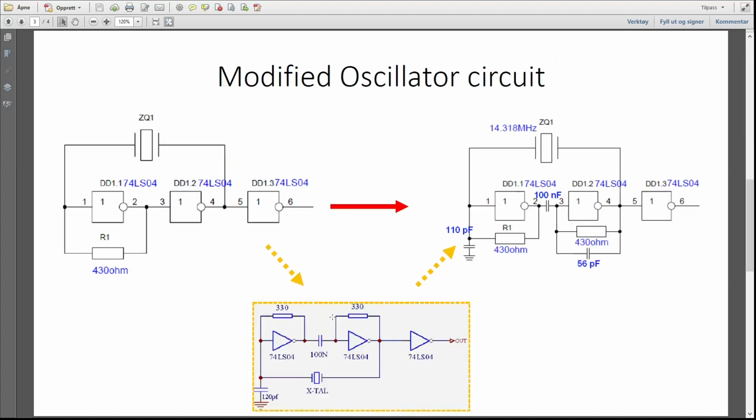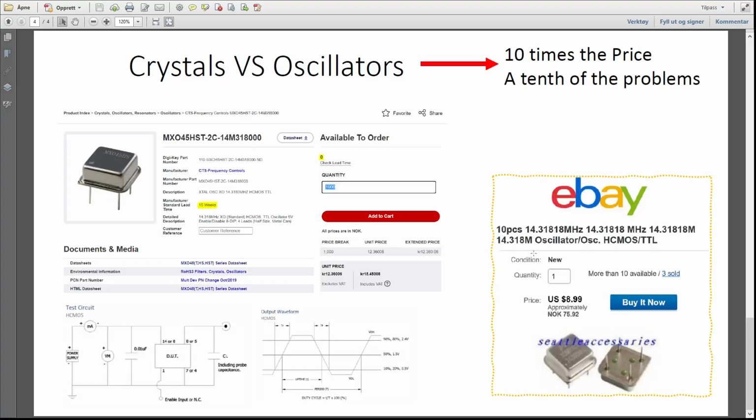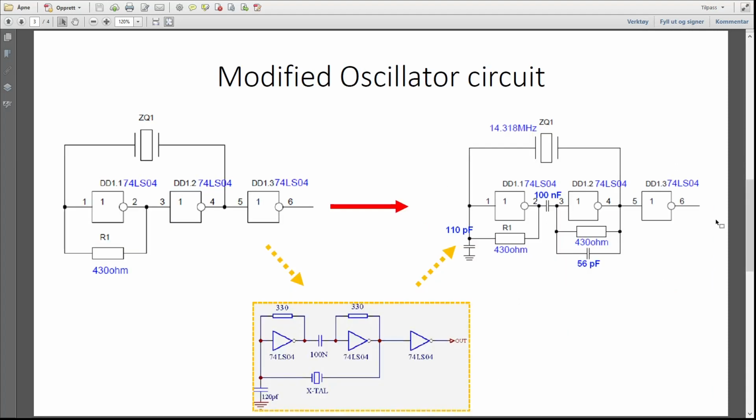A crystal oscillator like the one we have here can be prone to frequency drift and instabilities, and it's also possible that even though we have got it to work, there are some borderline cases where this will drift out and you come to another point and maybe it switches again to resonance on a higher frequency, as we saw in the start. This will be the permanent solution, I think, but until then we will try to get the circuit working with this one.